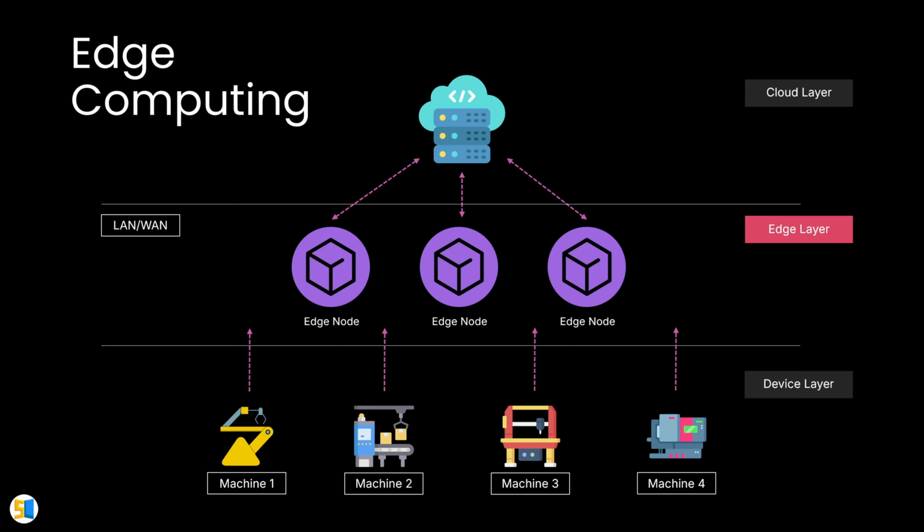The benefits of using edge computing are, first, real-time data collection. Edge computers are placed on the factory floor. The data latency is small because it uses a local network. Second, on-site data processing. The edge computers analyze and convert raw data using a packet analyzer and parser, for example converting data from PLC to OPC UA protocol. This enables immediate insight into production status without relying on cloud processing.